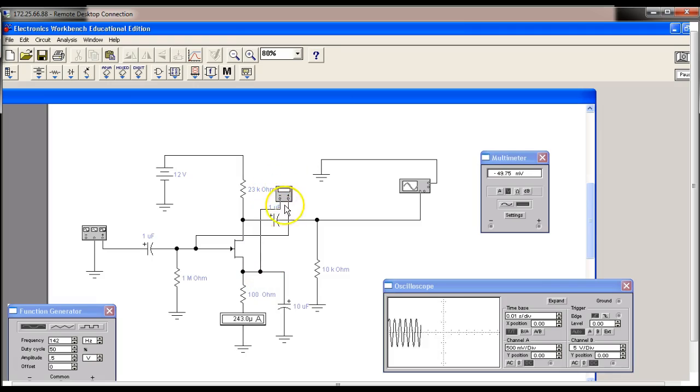So what we're going to say is, okay, if I put my negative here, and then I measure to my base, my gate, what we come up with is the gate actually sees a minus 51 millivolts, which starts driving the FET toward cutoff. Remember, in an FET or JFET, get those straight because we have different types of FETs, but on a JFET, you get maximum current flow through the channel when you have 0 volts on the gate. So what we do is we reverse bias that.